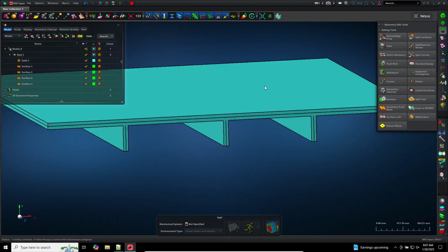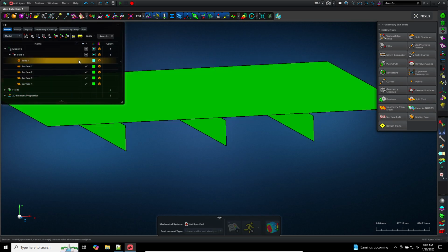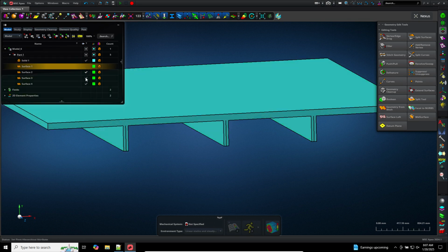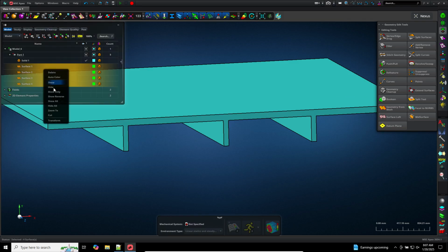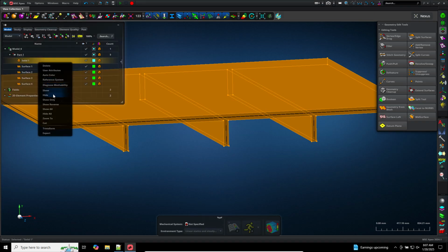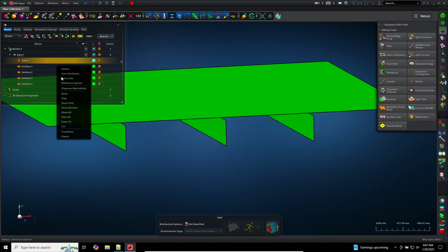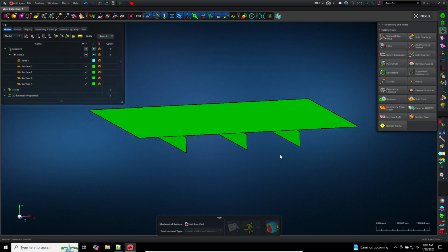One thing you'll notice here on the left, let's right click the solid and hide it. You can hide and show objects by clicking these individual checkboxes. I'm not a big fan of these checkboxes. I think these are honestly not optimally designed. So here, let's select multiple rows and show them. Right click on these objects and either hide or show them. I like using the right click option to hide and show. The checkboxes are not something I like to do.